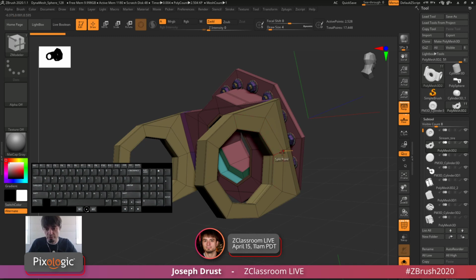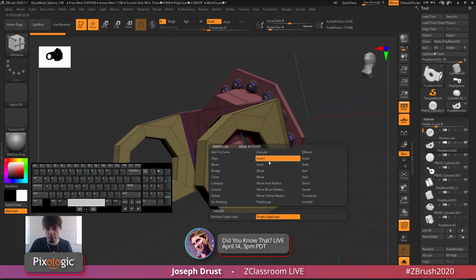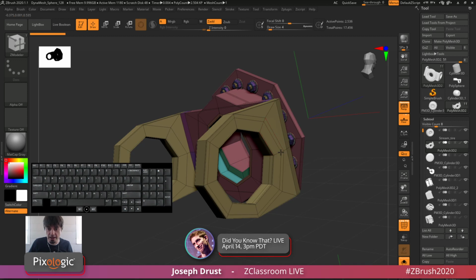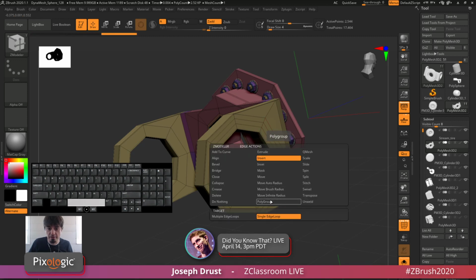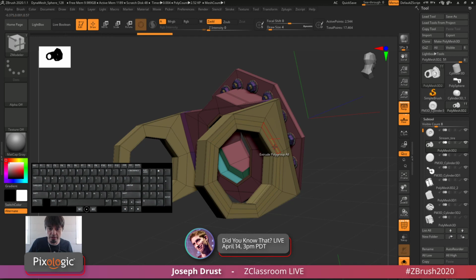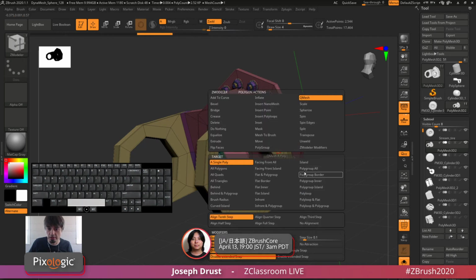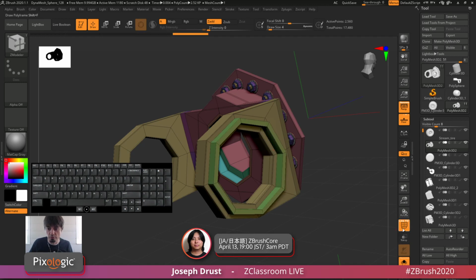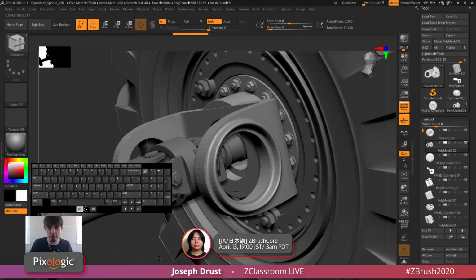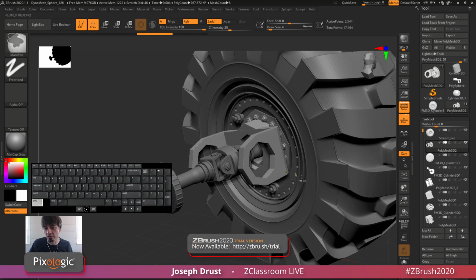But if you add this little protective loop around the edge, now if I want to come back in and say, hey, add another little design here, I've got that edge loop, right? So now I can come through and say add a little bit here to that part, and now I'm going to get a different result. If I didn't have that little protective edge loop that I modeled in initially, I wouldn't be able to do that, because basically the edge flow would not have worked.